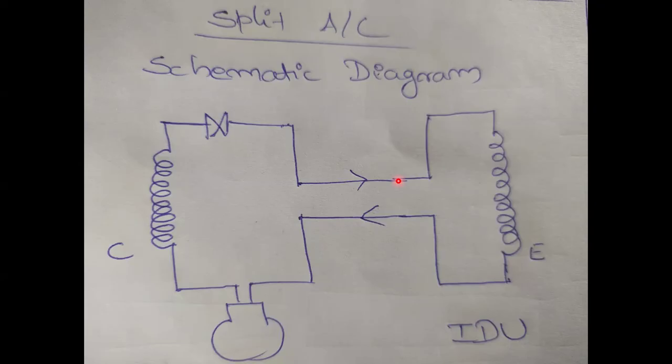And the compressors that we are using inside these machines should be either a rotary vane compressor or a scroll compressor. The scroll compressor is preferred for inverter AC machines. Okay, I told you that day itself. So typically, if you need an inverter machine, you must have a TXV, that is a thermostatic expansion valve, inside the circuit. So according to the load control, the scroll speed also varies. Okay, that's how you cut off the compressor according to the loads. Clear? And the throw length is still the same, guys, like 10 to 15 feet, 6 to 7 feet, that's it.